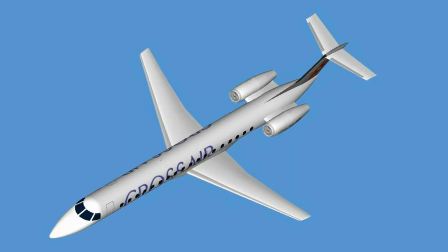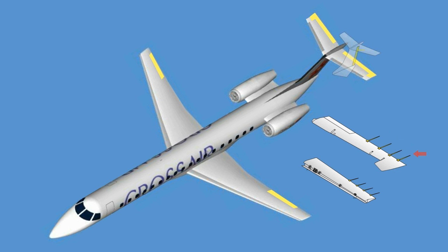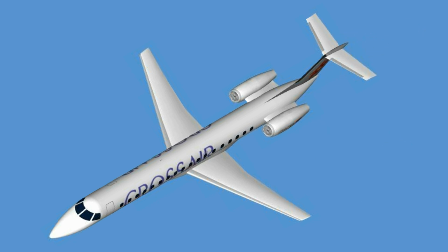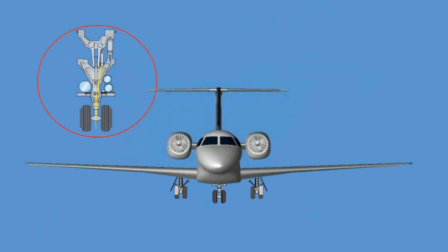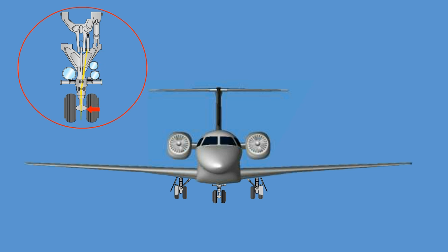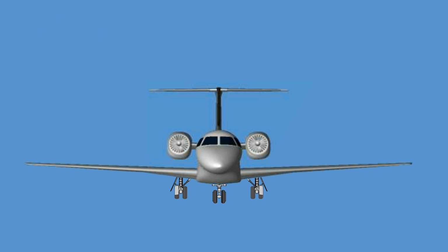Static dischargers on the Embraer 145 are installed on the following flight control surfaces: the ailerons, the elevators, and the rudder. Static dischargers are also installed on the wingtip fairings, on the vertical stabilizer rear fairing, and on the nose landing gear strut. Their purpose is to discharge the airplane electrostatic charges.